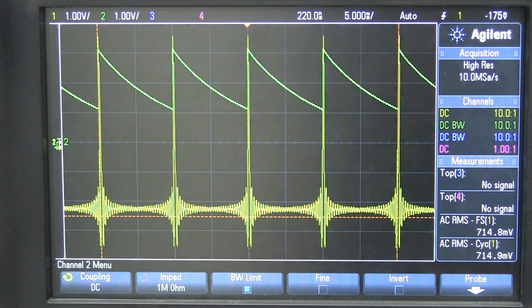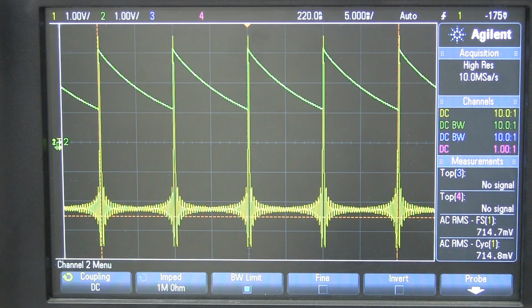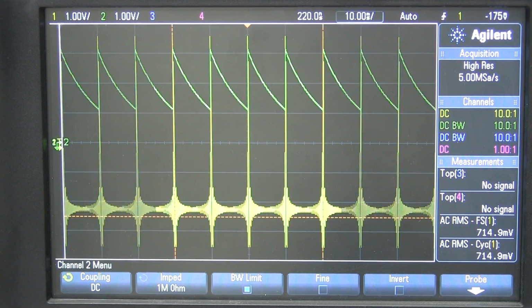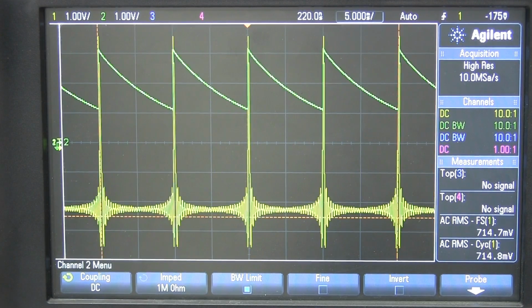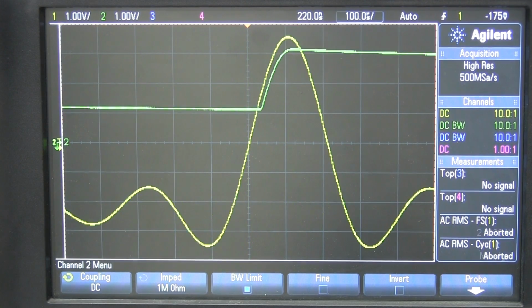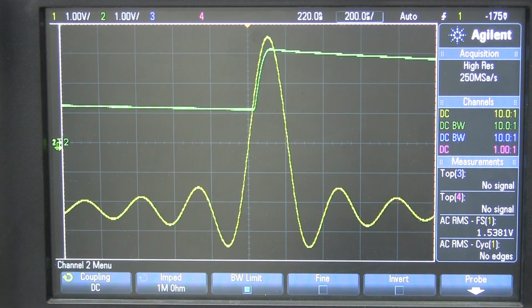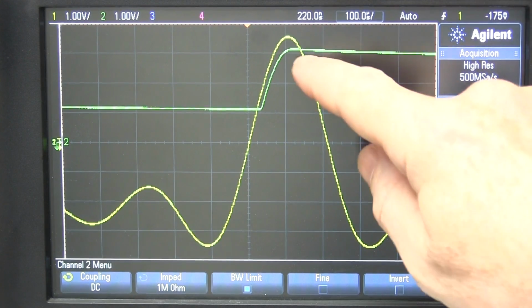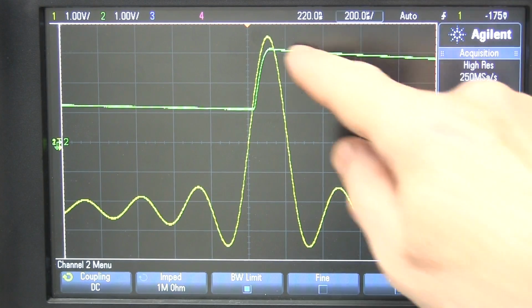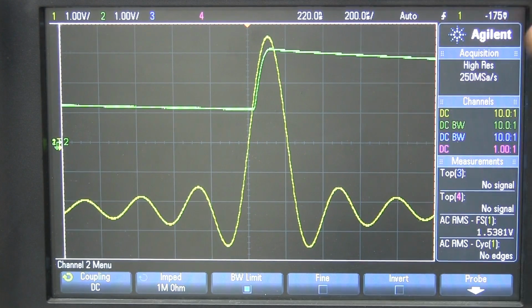And if we drop that down to a 1 nanofarad cap, right back at 1 kilohertz, you can really see the droop now. There it is. Pretty horrible, but that's what you get from 1 nanofarad, even with a 10 meg input impedance from the scope probe. There's no load on there at all. So look, you have very little time in there to actually read your value before it starts to droop off, and you get significant error pretty quickly.